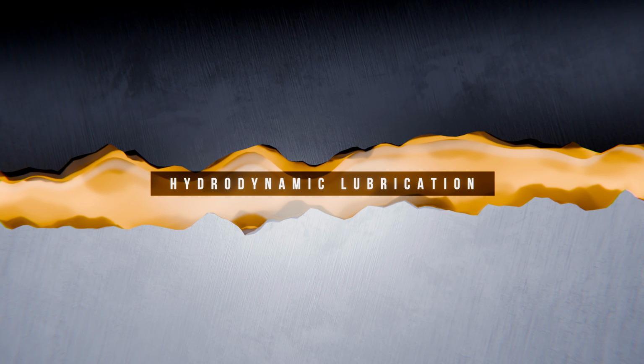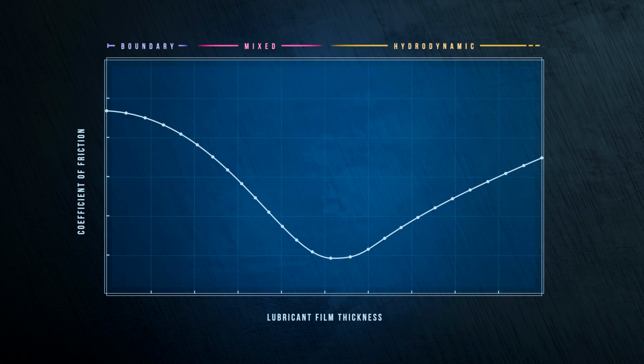The relationship between film thickness and coefficient of friction forms a characteristic curve. Friction is high when the film is very thin, but falls in the mixed lubrication regime as more surface asperities are separated by the fluid. It then rises again in the hydrodynamic regime once the two surfaces are completely separated, because more fluid being dragged between the two moving surfaces means an increase in viscous shear forces within the fluid, and so increased energy losses.